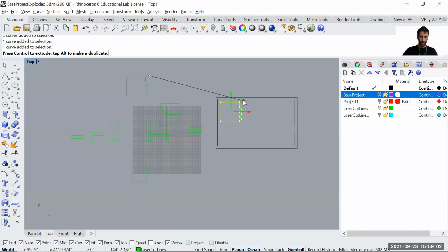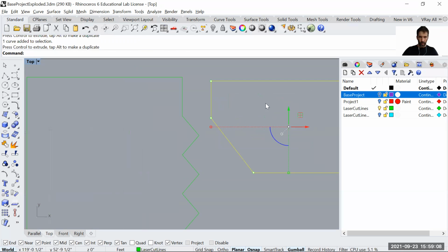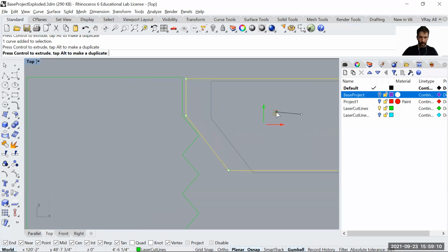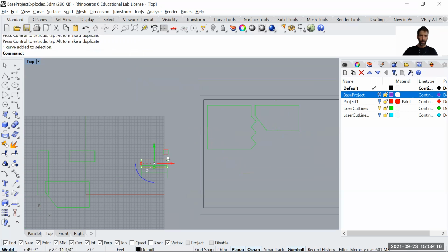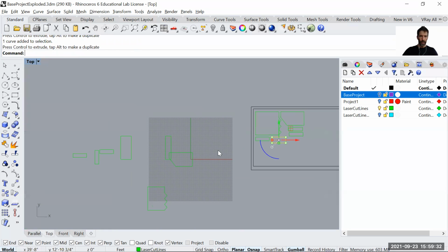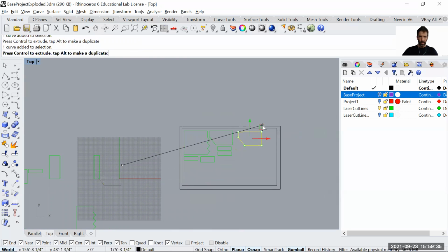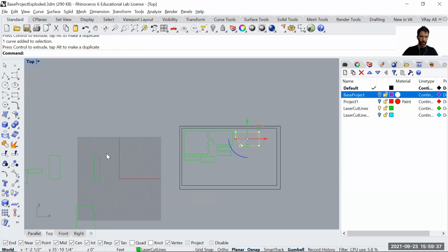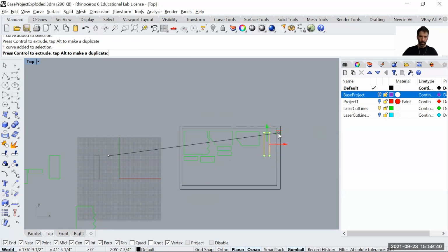You need to bring those in, nicely organized and as close as possible. You don't want to be so close as that. You want to be as close as you can so you don't waste material. There are actually other tools, very nice plugins for Rhino, that allow you to do this automatically, like just pressing a button, but we don't have that plugin. So it's not that impractical, nevertheless, to organize your line drawings in the template manually. You might be able to rotate.